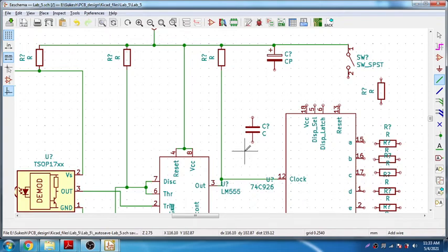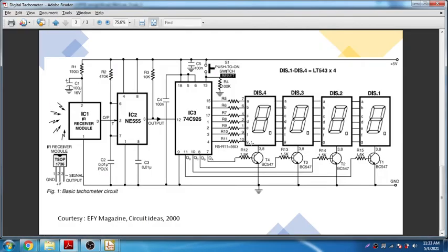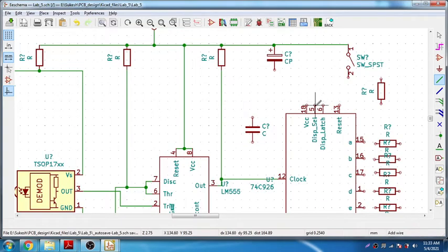So pin number 12 is connected, and this capacitor, what is it doing here? There is a 100 microfarad capacitor over here as well. One end is connected to the supply. So pin number 18, 5 and 6 are shorted, and all these are connected to VCC, if I'm not wrong. So this should be connected to VCC over here.